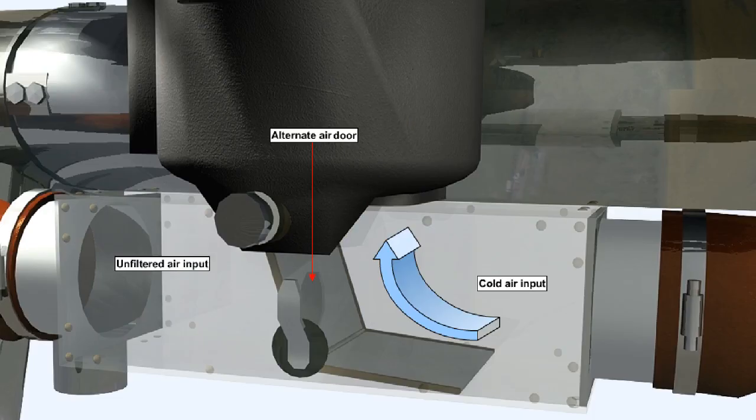It's generally accepted that the fuel injection units used on the engines used in most light aircraft do not need heated air for the purpose of induction Venturi icing protection. However, it has been suggested that operators should consider incorporating an alternate air door as a means of preventing manifold air starvation caused by filter blockage from icing or other ingested materials.